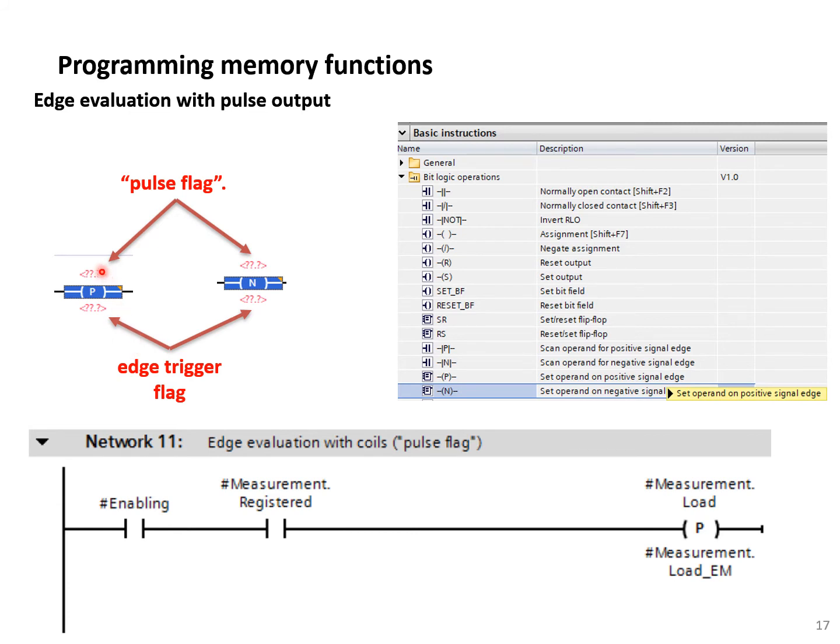So when the pulse flag goes from, let's say, 0 to 1, we have a pulse trigger or positive edge output, and for one cycle only the output will become true. However, each trigger flag will keep the last state of the pulse.